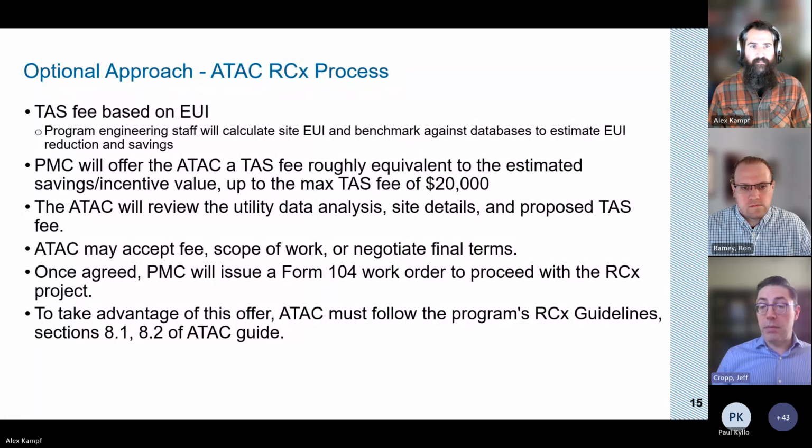A lot of that is trying to make sure that you are doing trending during a season, or have trend data at least. If someone's already set up the trend data and you've got trend data for a year, that's great. You can just move forward. In many cases, people have not set up the trend data, so you have to set up the trends.